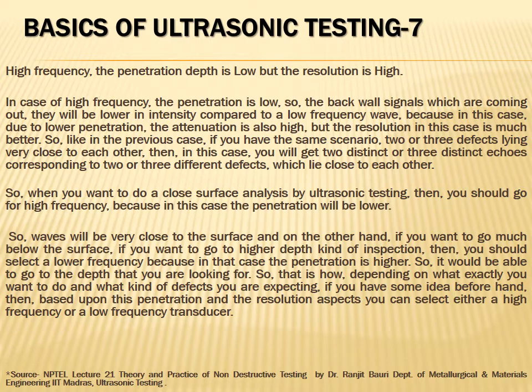So when you want to do close surface analysis by ultrasonic testing, we go for a high frequency, because the penetration will be lower. At the other end, if you want to do an inspection in depth, we should select a lower frequency, because with lower frequency the penetration is higher, so it is able to go to the depth you are looking for.